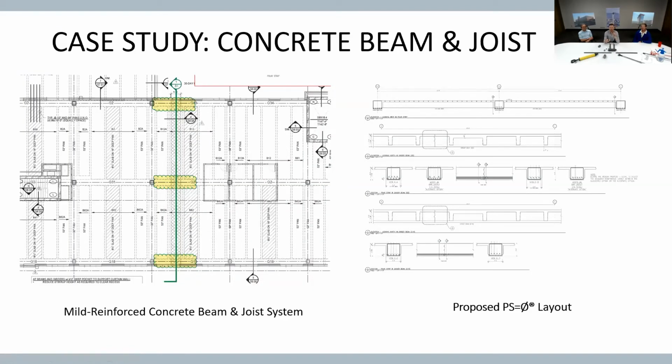There you go. This was something that we explored and detailed, and because this beam is a very significantly loaded member, we have couplers going on both sides of the pour. Originally we designed this to really have it go on the first pour, but it could go on the second pour. But on this one, we're actually putting them in both so we could fit everything in together. This is being submitted right now, and we're waiting for some feedback. We had some initial discussion with the contractor and the engineer of record to get everybody comfortable.